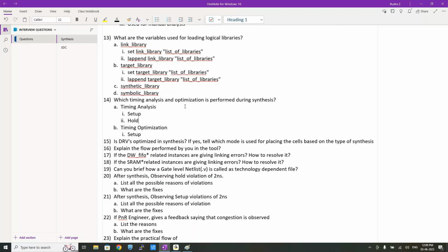First reason: the clock tree is not built, so hold optimization will not be done. Second: hold analysis is done after the synthesis stage to make sure we have not missed any exception with respect to hold, or any disturbance in the SDC file.